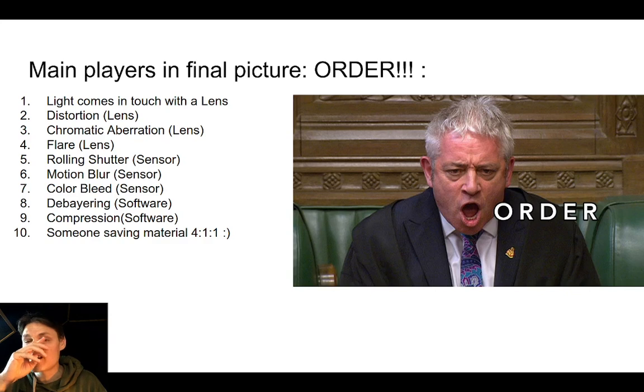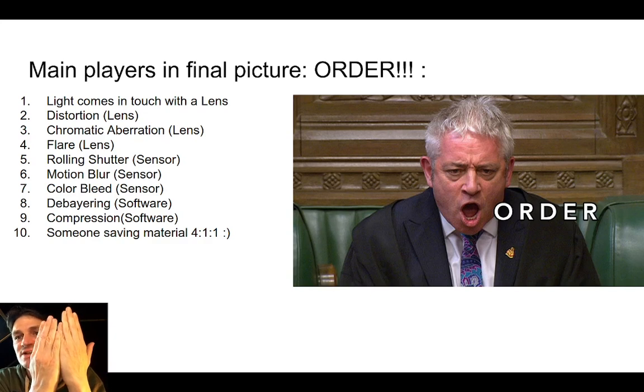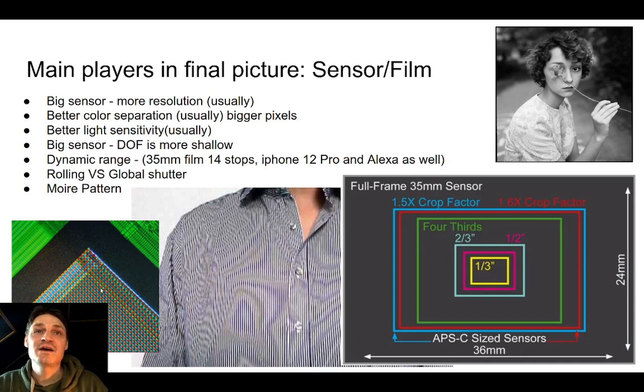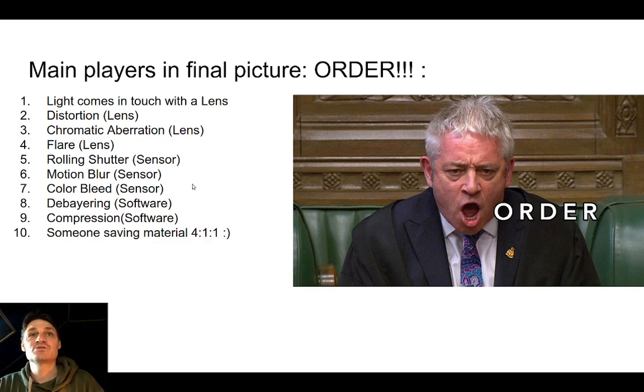For example, we have very strong green and very strong red standing next to each other. The sensor starts to get a little bit nervous and crazy, and red pixels or green pixels go on top of the red in certain channels, because in certain areas it was not able to properly grab the material and put it in the proper place, and it's called debayering, okay.